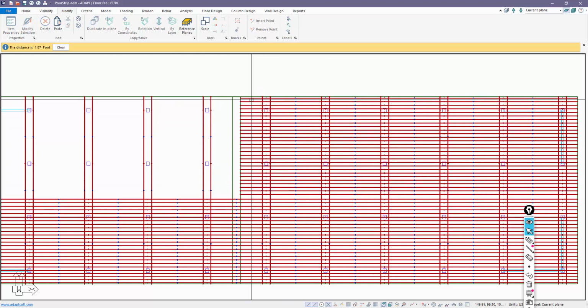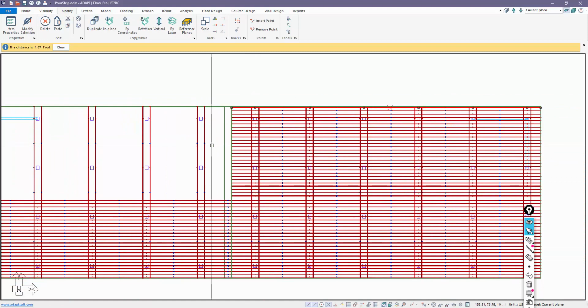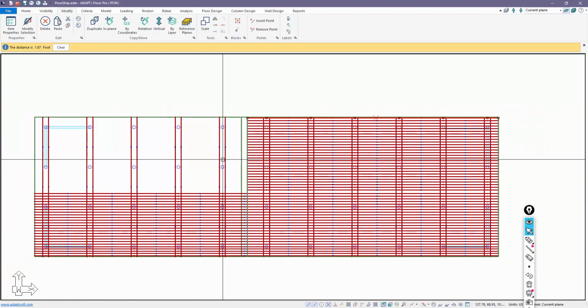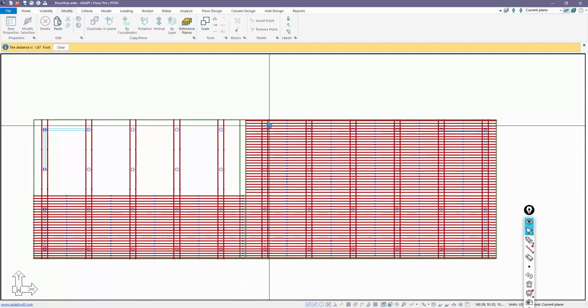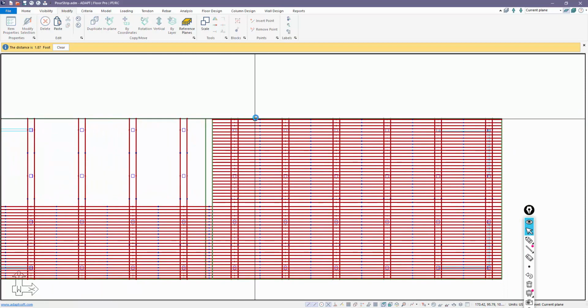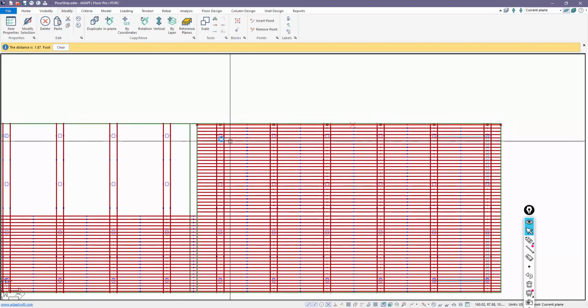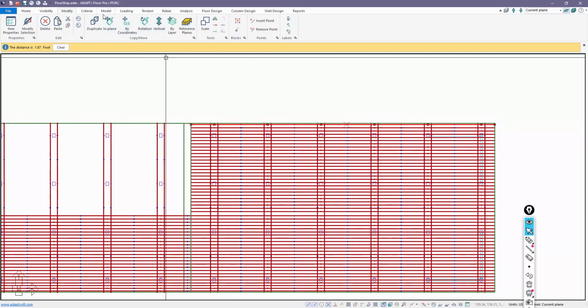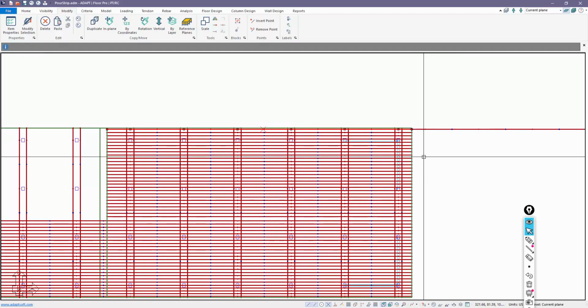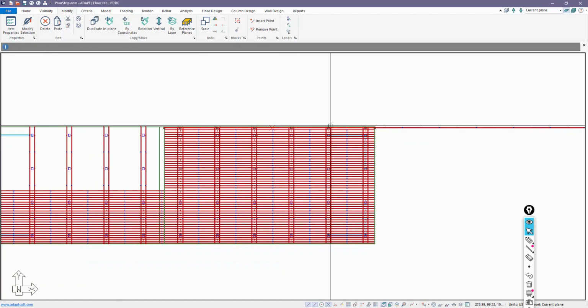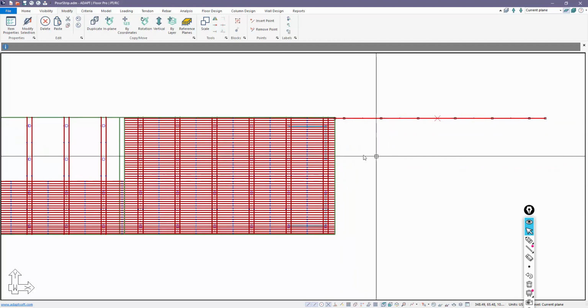Now, what I will do with this cable, the first thing I'm going to do is copy it. So I'm going to mirror it first, and then I'll copy. Okay, so we're going to select the tendon, and we're going to go to the option modify, and we want to mirror this. We're going to mirror it off of this point, and the end point will be that slab edge. So we have a vertical mirror line, and this becomes our new tendon.